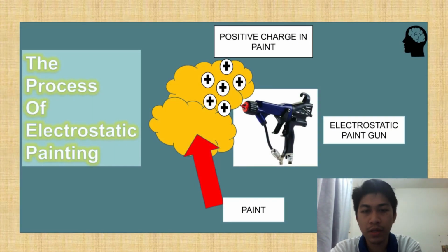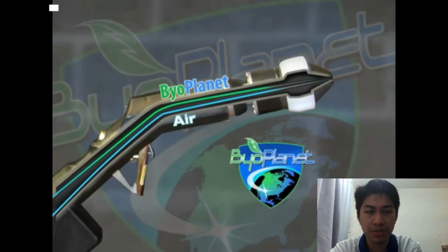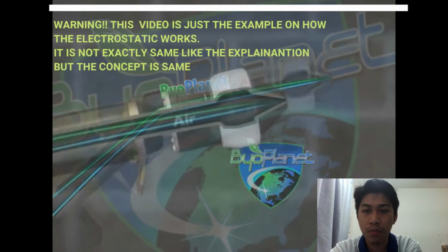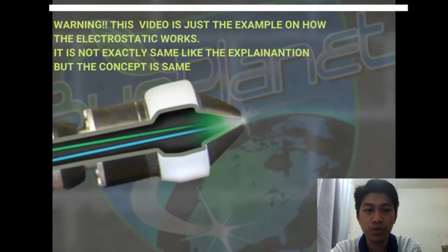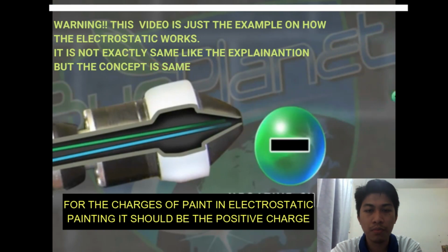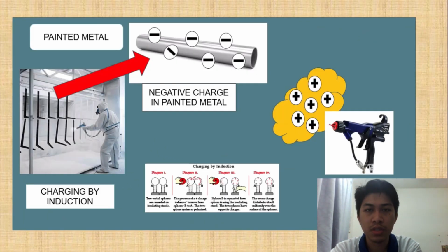Firstly, as we begin the painting process, we use the paint gun equipment to fill the paint in the paint particles. The paint is added to water, then combined with high pressure air as it moves through the nozzle of the spray gun. Electrostatic painting equipment will atomize the paint, referred to as the process of ionizing paint particles, making the paint highly positive, while at the same time the metal will be charged inductively.